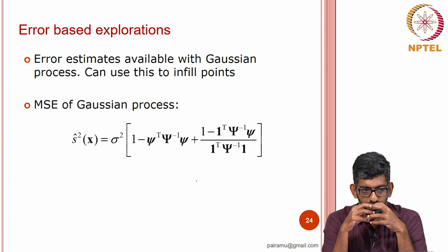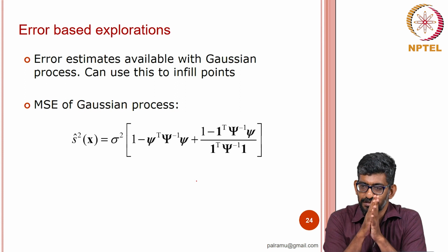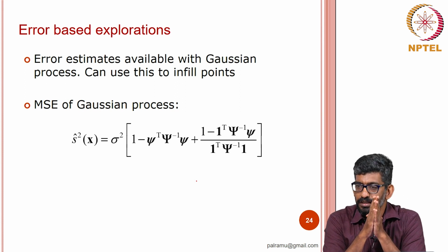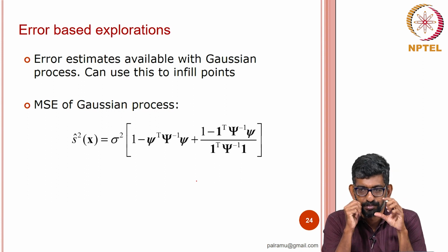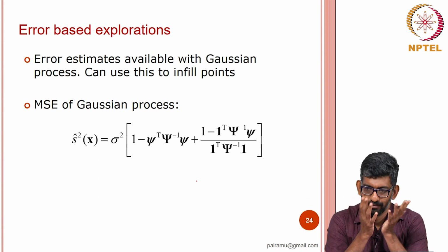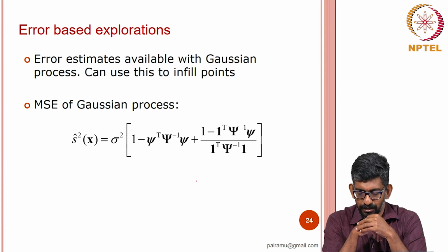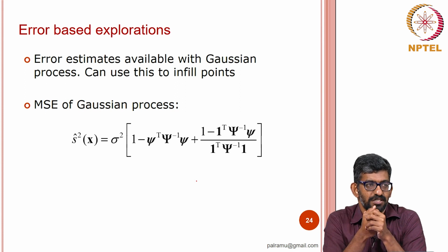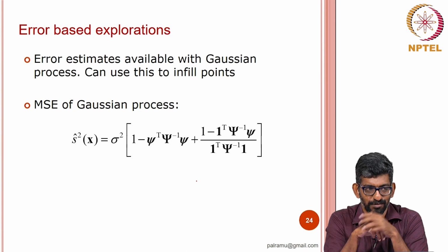Here the discussion is focused on the Gaussian process, but at a later point people have also shown that the error metrics or the uncertainties in the predictions from one model can also be imported to another model. For instance, in Kriging you have a Gaussian predicted variance. A polynomial response surface does not explicitly give a prediction variance, though it implicitly gives it in terms of R squared.